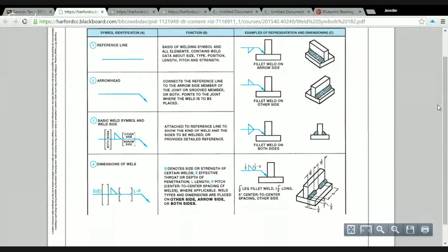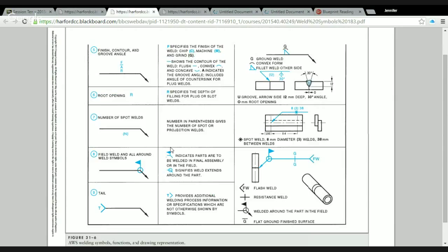Welds. Yes. I'm going to wrap this up real quick, guys, because I know it's getting long. But fillet welds, once again, the side of the arrow, the side of the reference line that the symbol rests on, please remember what that means. Please remember that the value to the left of the symbol indicates how large the weld is. And finally, that the circle around the arrow means you're welding all around. And that's the basics of what we're doing there.